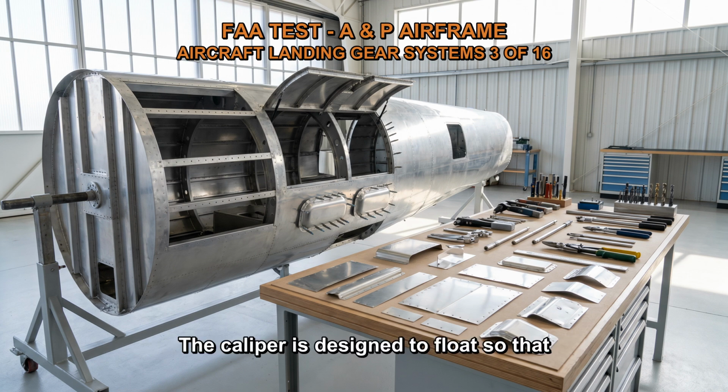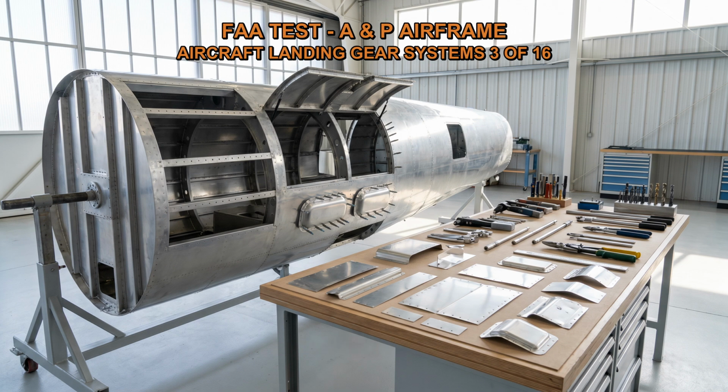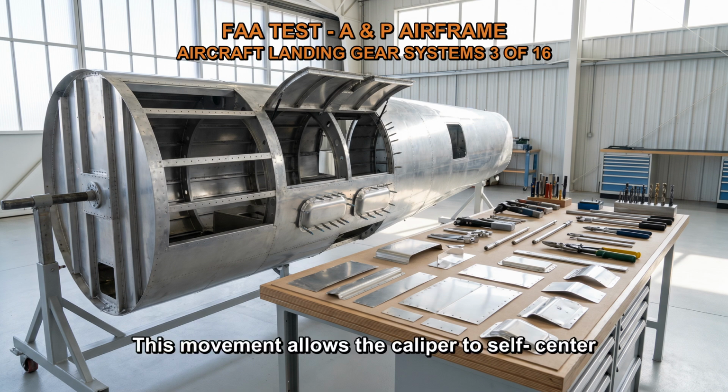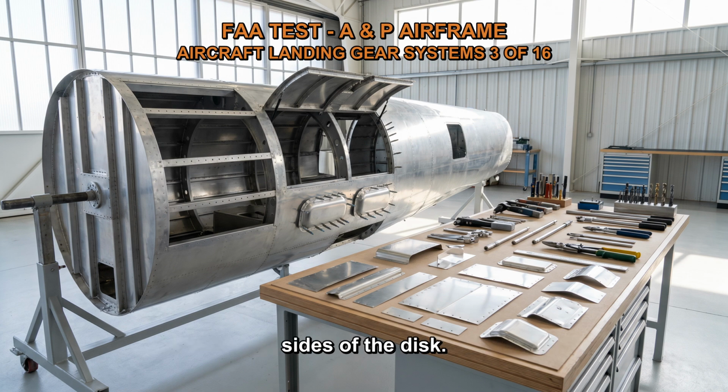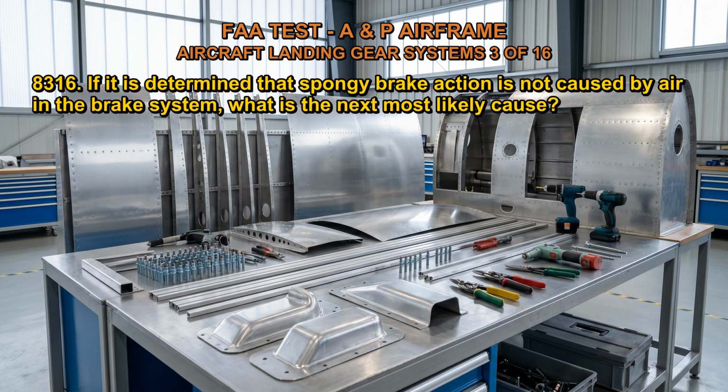The caliper is designed to float so that it can move slightly in a direction perpendicular to the brake rotor. This movement allows the caliper to self-center on the rotor, ensuring equal pressure on both sides of the disc. This design allows the brake system to function efficiently and ensures even wear on the brake linings.